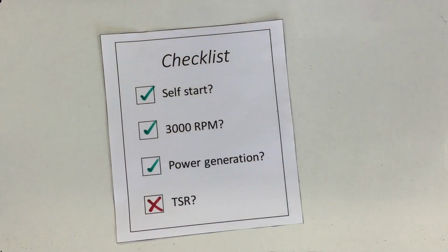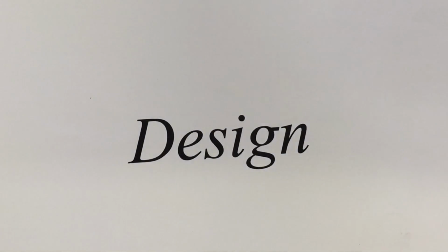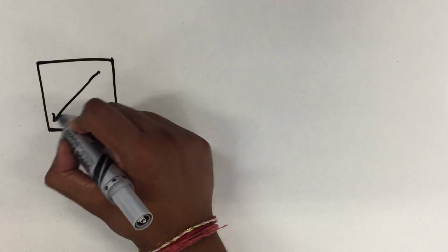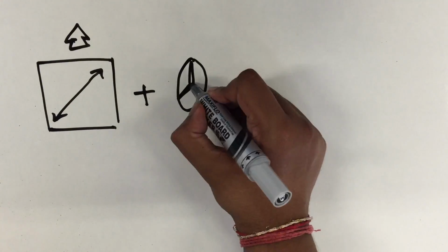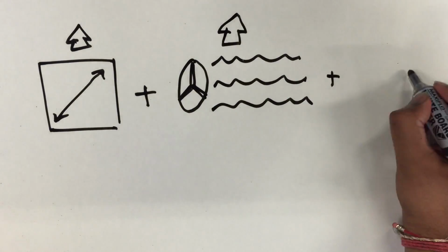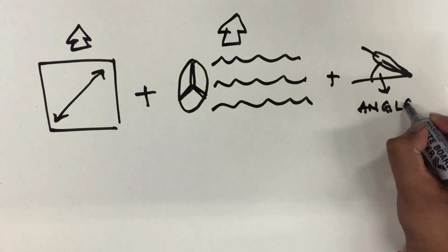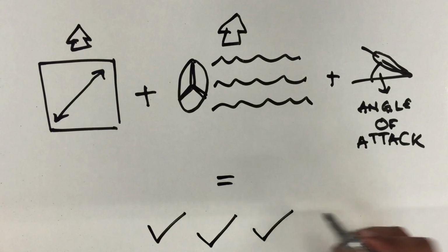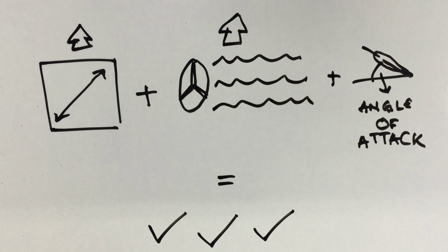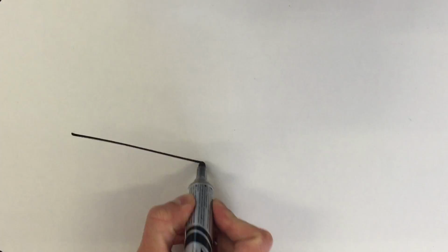To evaluate its performance. In designing the turbine blade, we first needed to consider some turbine blade physics. In brief, turbine blades perform better with greater surface areas and greater incident airspeed. The angle the blade makes with the incoming wind is called the angle of attack. The performance of a given cross-sectional blade profile, or aerofoil section, depends on the angle of attack. Different aerofoils also perform differently at a given airspeed.